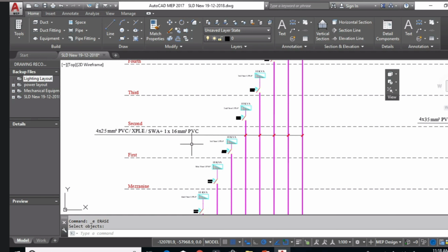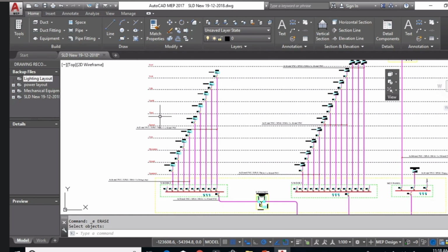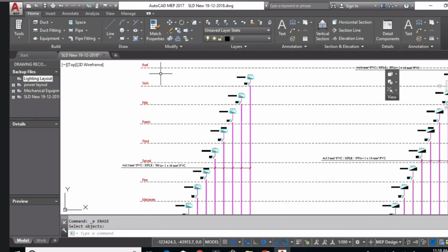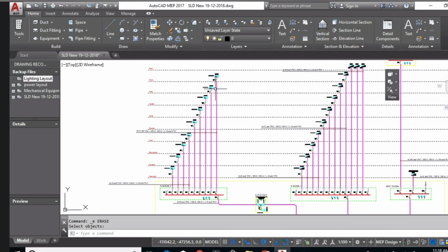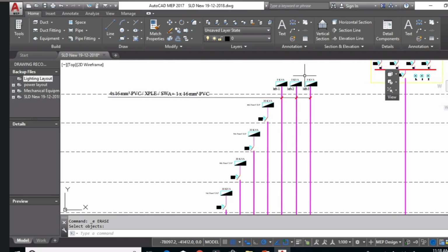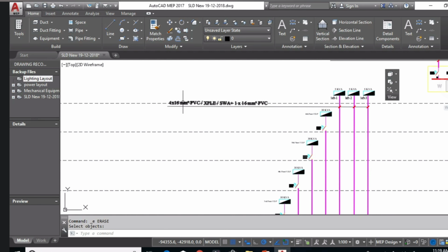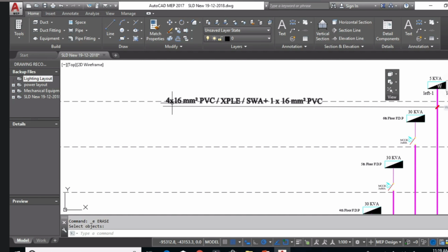And here, see, this is a cable here. To take these lines from a section, the center line, to calculate the distance from the MDB to the final distribution panel. And as you know, it is important to calculate the volt drop. And here, also for the elevators on the essential load, the cable is 4 by 16 mm.